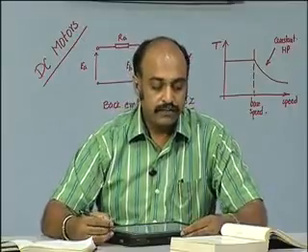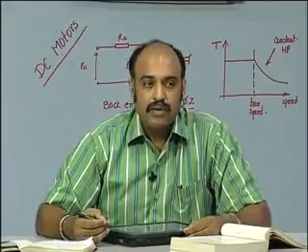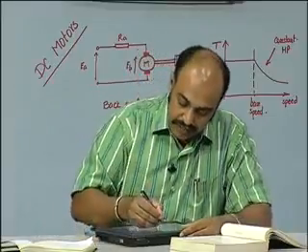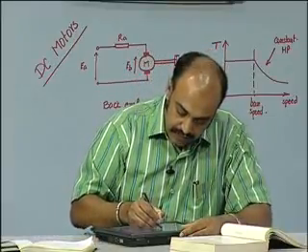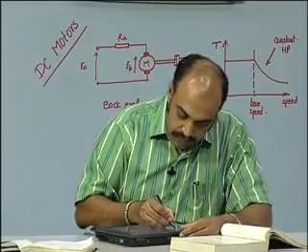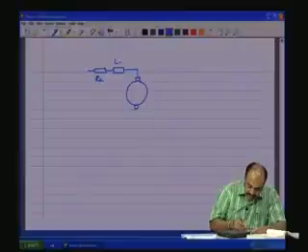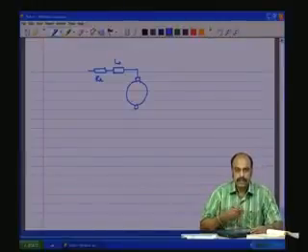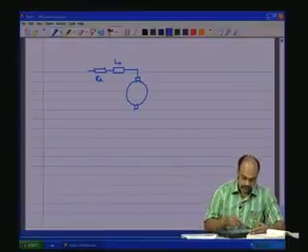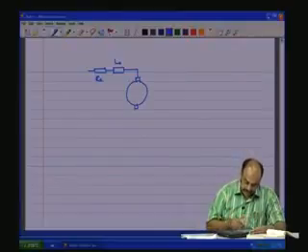So, now finally, we would like to discuss the state space model of the DC motor. It is very simple, just like in the case of the generator. So, we have the motor, we have RA. Now, I am going to include the dynamic element LA, which is going to cause the rise time and fall time of the motor. So, the LA is going to come into the picture, which is nothing but the armature winding reactance.